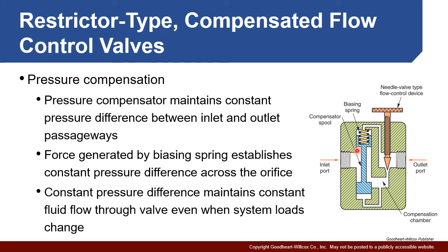It's going to push on this piston and compress this spring, and it's going to close off this portion of the valve, and this is what this whole compensating chamber accomplishes. If the pressure then drops, this valve opens more and allows more flow. So this prevents high pressures and pressure surges from causing greater flow through here. So this compensates for it.